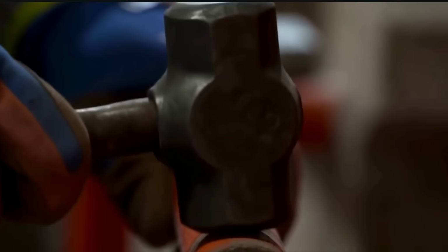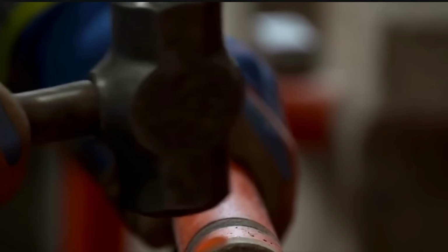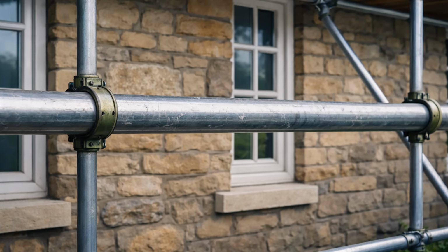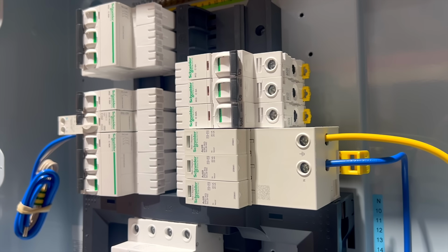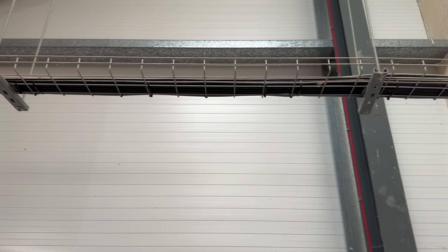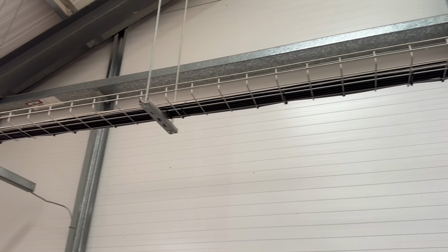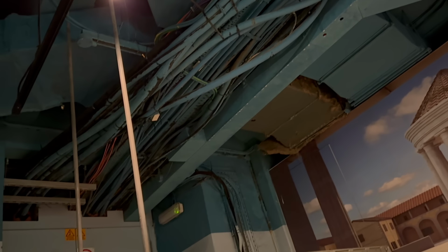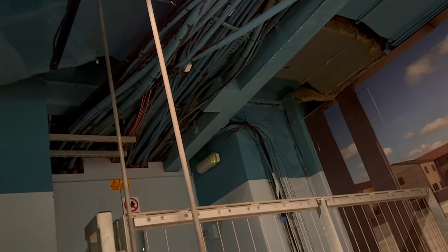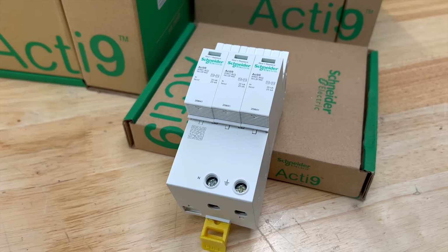Imagine striking one end of a long scaffold tube with a hammer. A shock wave travels along the tube and it is felt at the other end. And a surge behaves in a similar way. The SPD limits the voltage at its own terminals to its declared UP value. But a voltage wave travels along the conductor towards the equipment. If that conductor is long enough, the voltage at the far end can briefly be significantly higher than the voltage measured at the SPD itself. And it's this that the regulation is describing as oscillation. It's not the SPD failing, it is the cable becoming part of the surge circuit.